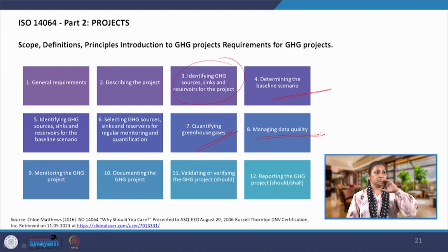For example, HVAC conditioning, a lot of energy goes into conditioning. We have to know specifically how much is going into artificial lighting of the place, and how much is going into the air conditioning. If I know that artificial lighting is consuming a lot of energy, maybe I will specifically look at the design issues or the change of material to bring in some daylight and reduce my consumption of energy for artificial lighting.